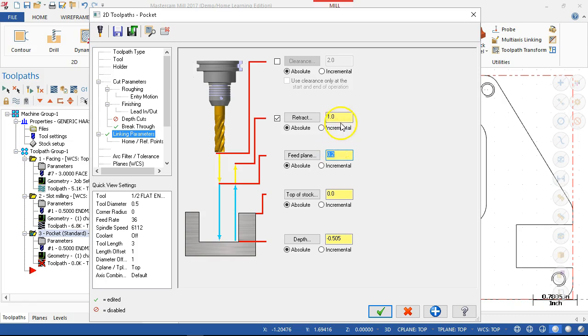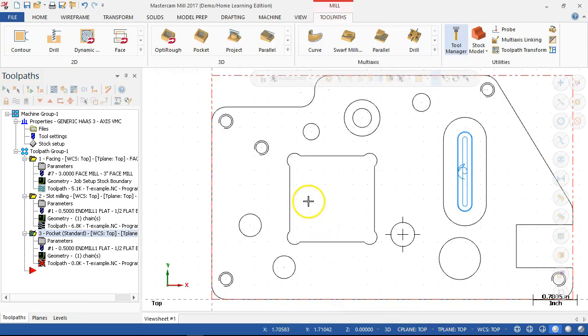As long as we can clear clamps, or we're moving around inside the part where it's not going to be an issue, fine. But as soon as we jump over where there's a clamp, that value has to go up. Hitting clamps is never a good time. Did it add the 505 for me, or was I not paying attention?